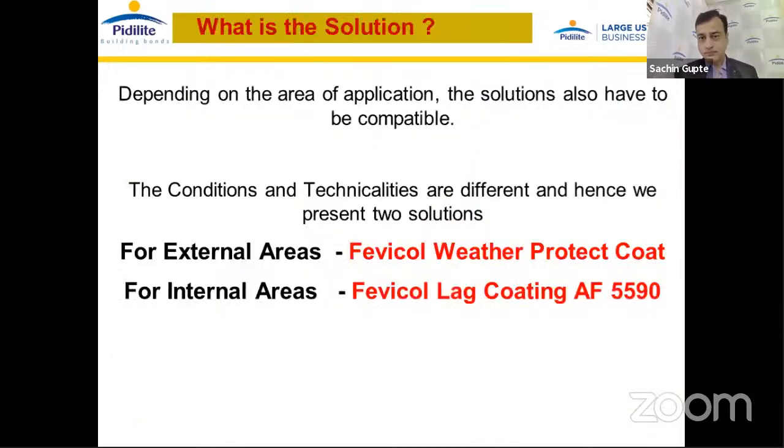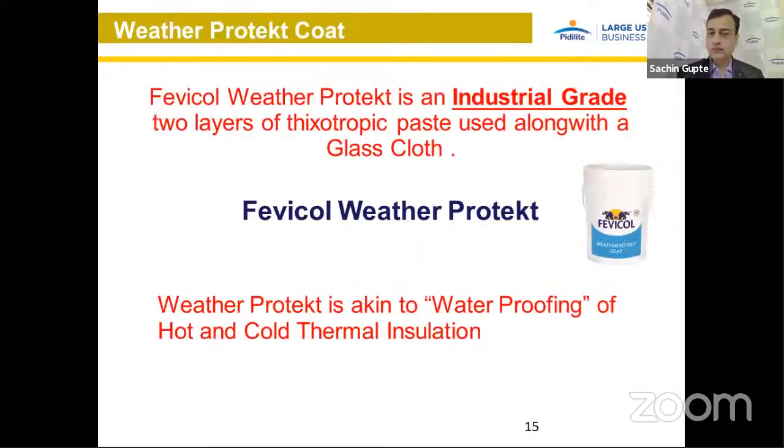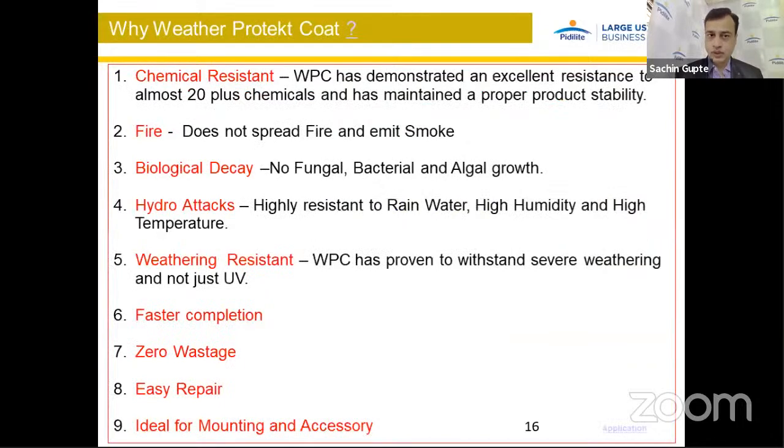Yeah, sure. Depending upon the area of application, we have two different types of products. For external areas, we have Weather Protect coat, and for internal areas, we have Lac coating. Both the products are coatings. These are brushable coatings, industrial grade thixotropic pastes, which are used along with glass cloth, which acts as a mechanical reinforcement.